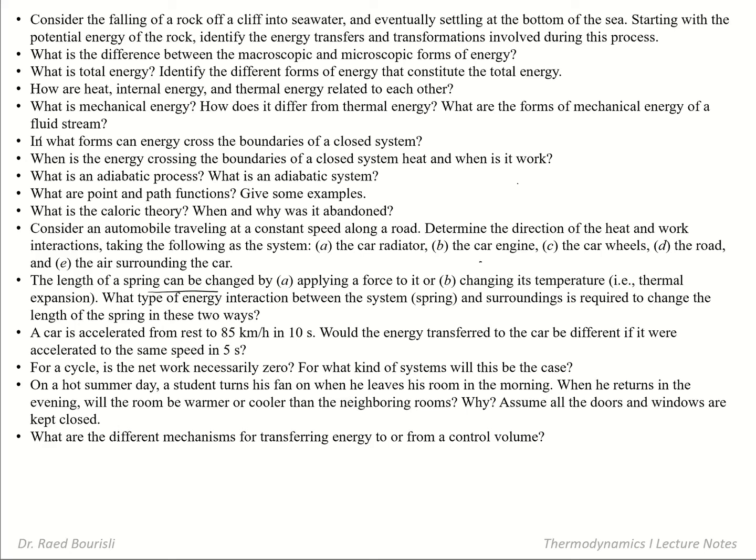The length of the spring can be changed by applying a force or changing its temperature. So what type of energy interaction? If you compress it, then it's a work interaction, and if you change its length by changing its temperature, then it's a heat interaction.